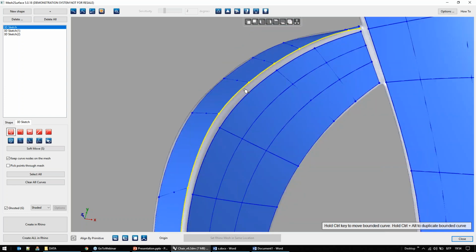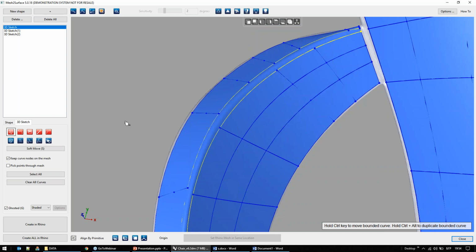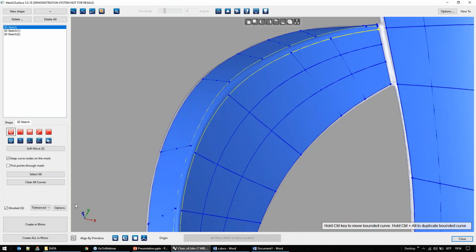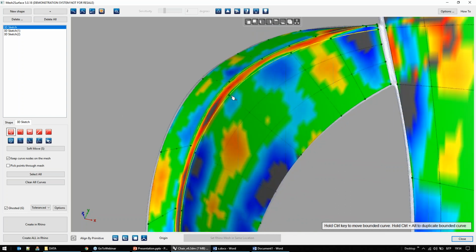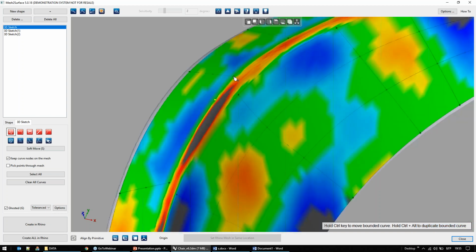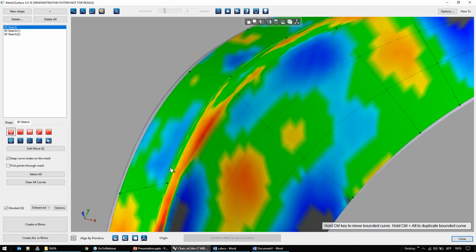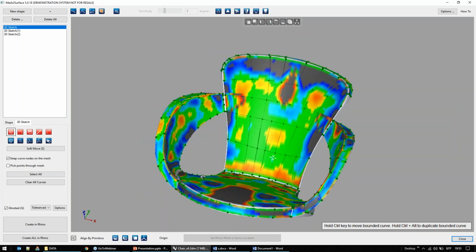Again, why blend surfaces? Because once you create a blend surface, the interactivity is still here, so by manipulating the surface, you can always see what your object is like and how close you are with the surface. You can move the curve and you just get your result.